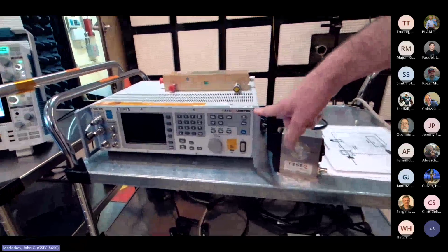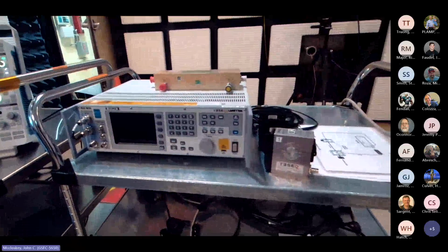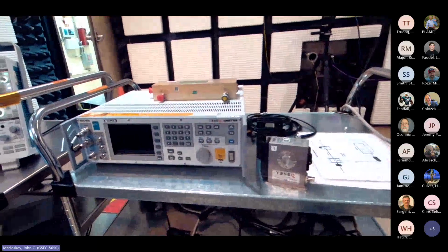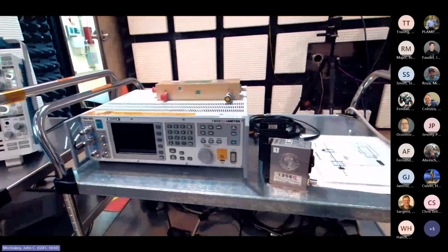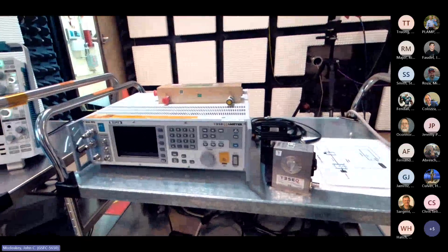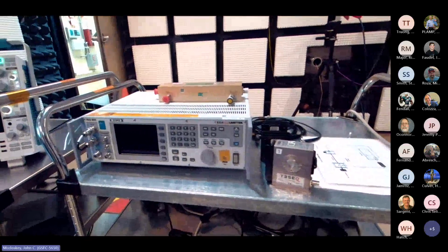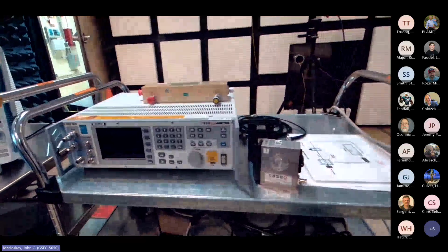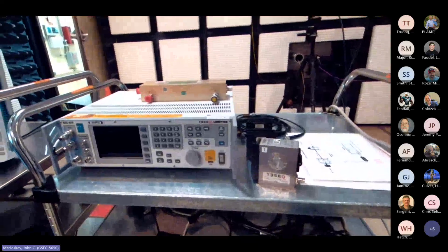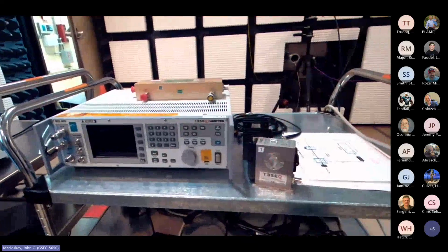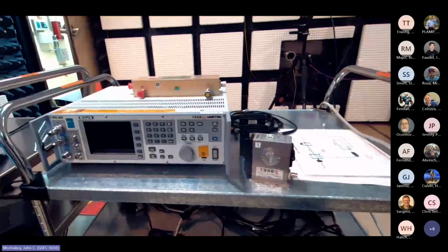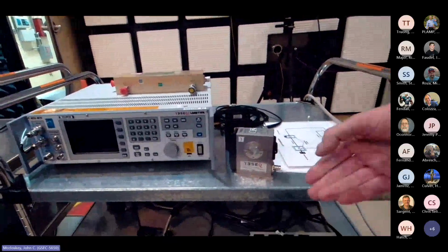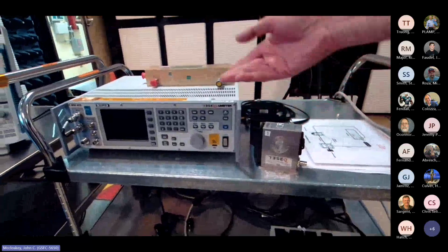But one point I will make is that when you're doing power lead injection, you do need an amplifier to get to the higher levels that you need at low frequencies. As we'll talk about, the insertion loss of the injection probe is substantial at lower frequencies, and to get the desired signal at 10 kilohertz and up to about 1 megahertz, you do need an amplifier. But for common mode injection, which is what I'm going to show today, for the low level signals that we're injecting, you can do it without an amplifier. So anyway, I just wanted to show you this system here.